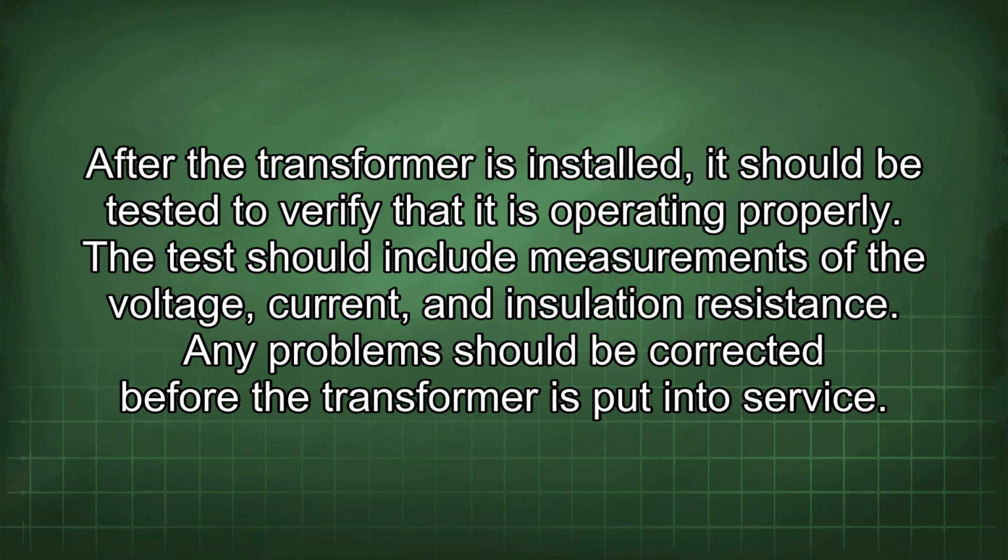After the transformer is installed, it should be tested to verify that it is operating properly. The test should include measurements of the voltage, current, and insulation resistance. Any problems should be corrected before the transformer is put into service.